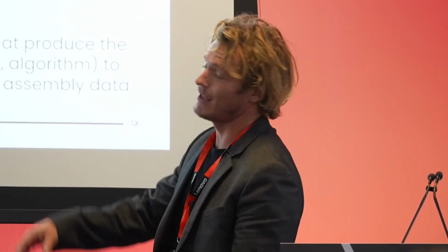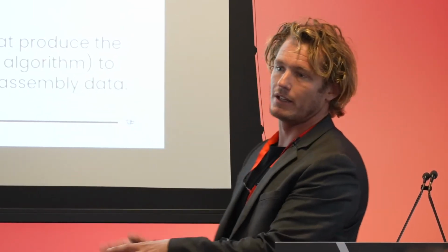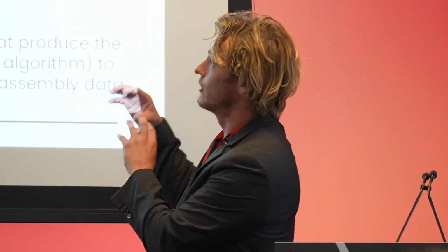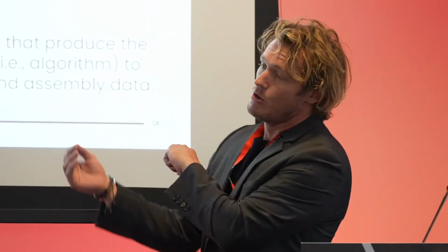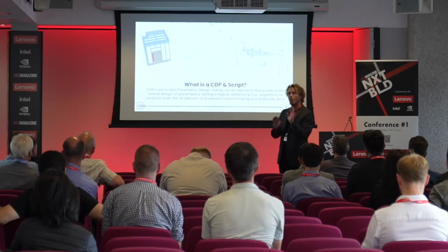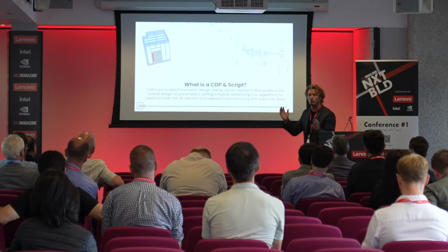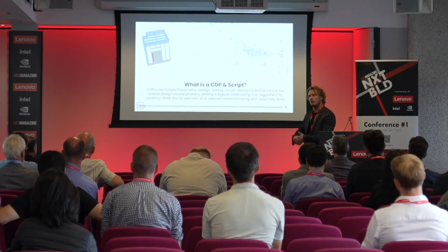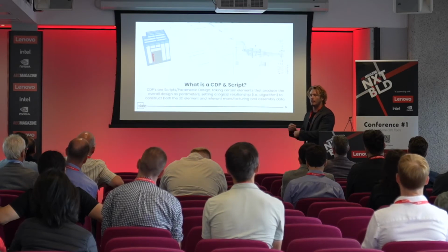What that then allowed us to do was to really start to look at the efficiencies in how we were designing that. We were spending less time having to engage with the architects and with the GCs and educating everybody on how we were going to design it, and more on how we could create our product more efficiently. So that was where we started to look at the nesting of that sheeting, and we could see that it was actually more effective for us to put a steel member and not to have all vertical sheeting. We could actually rotate it, and we could do what was necessary to get material efficiency. And then we could really look at the assembly as well and start to create ledges and details so that the assembly could follow.